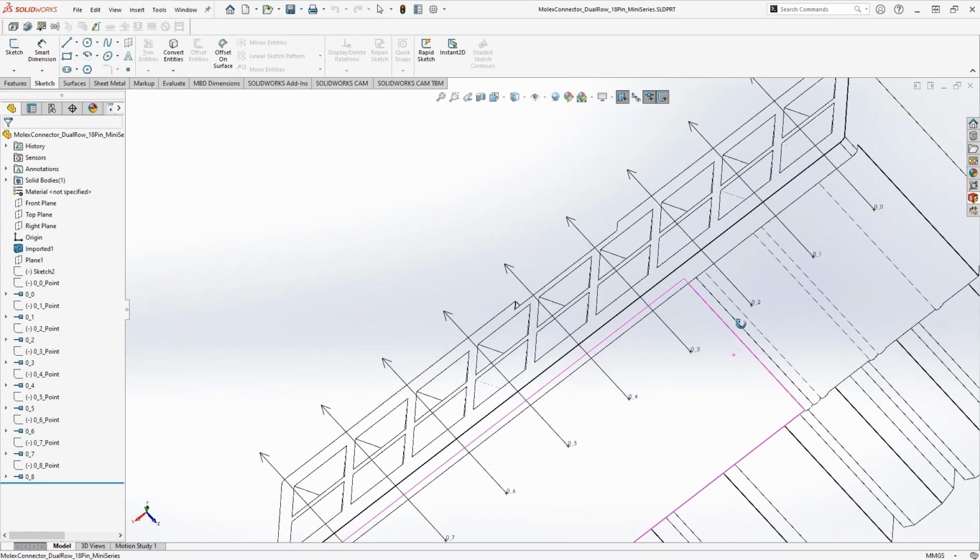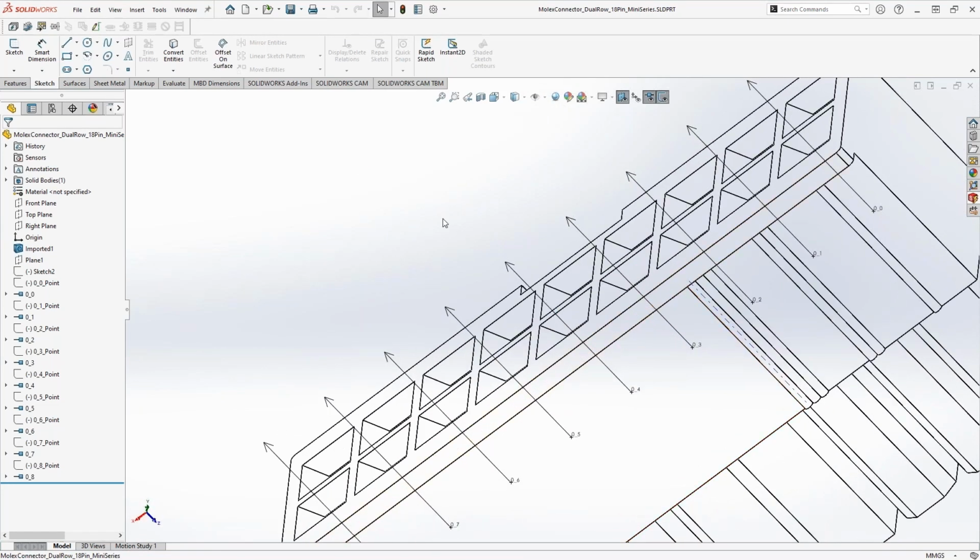Those are the connection points for every single one of the wires that I'm going to route. In reality, I probably should have created connection points for the entire top row as well, but this is just a demo to show you how the wires will route at some point. But you can see that those numbers there correlate exactly to the manufacturer part. So when I put a wire on pin 1 in my schematic symbol, this is exactly where it's going to route to.